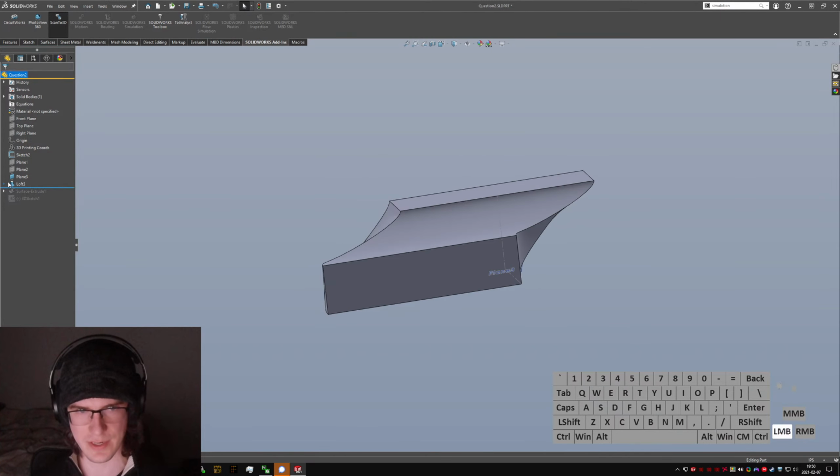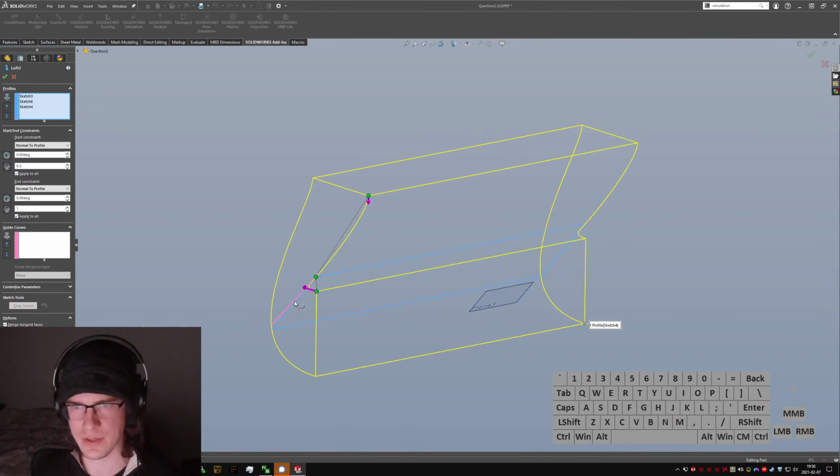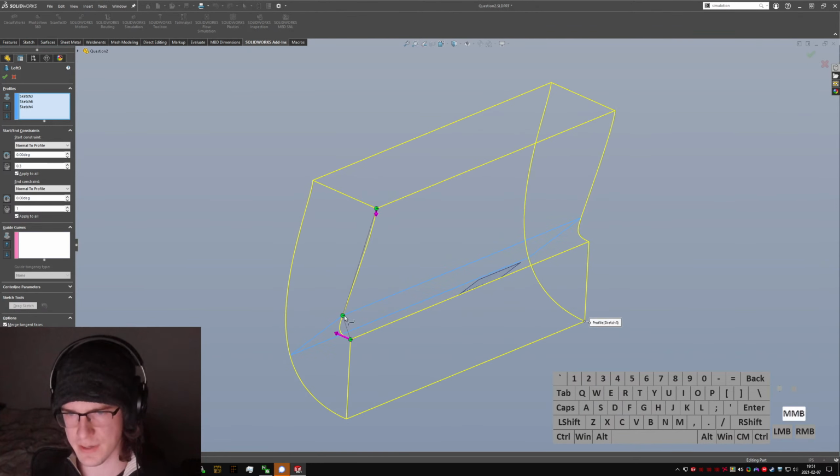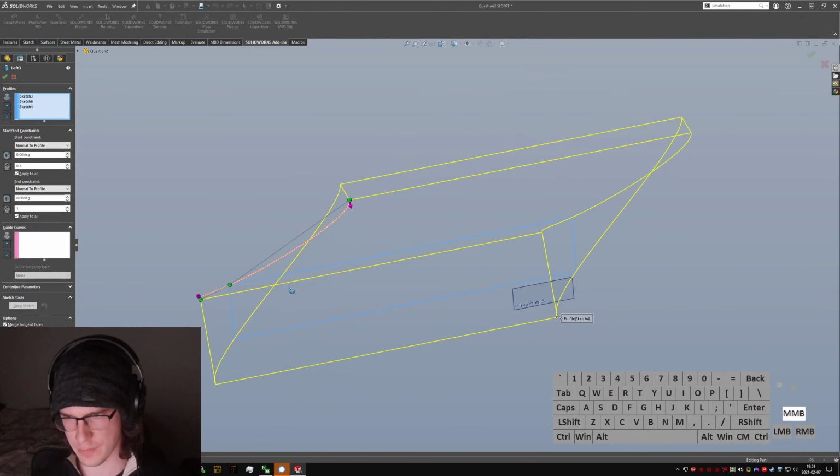But this method, adding certainly the first trick of controlling where these green points are is how you control how your loft profiles rotate and how they're connected to each other. Always a good idea to have the same number of points in all of your loft profiles, that way things don't disappear or go into the void. You can control for that with guide curves, but it's a lot of extra effort sometimes if you don't want to have the splines and you just want to let the loft tool do everything for you. In this particular case, adding an extra profile works just fine, but sometimes, maybe if you're doing drafting for a ship hull or that sort of thing, it can be really hairy real fast.